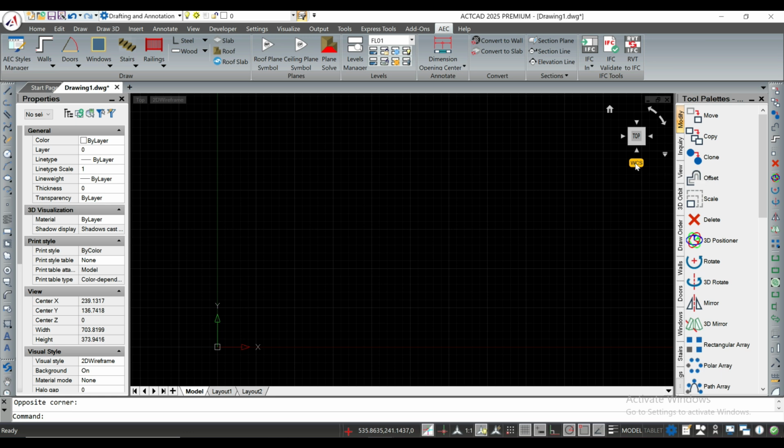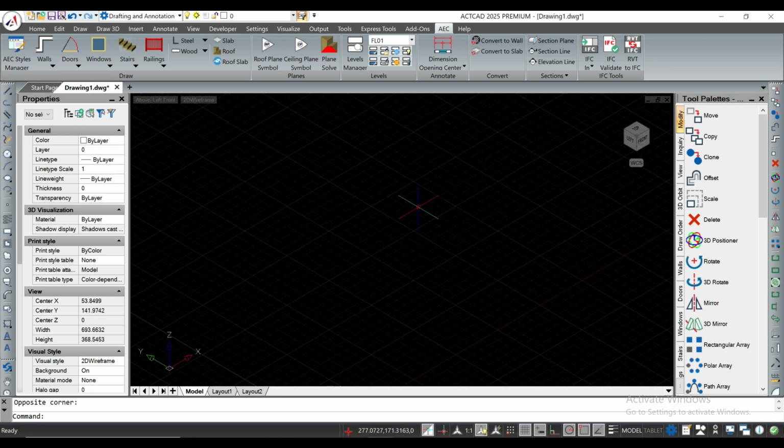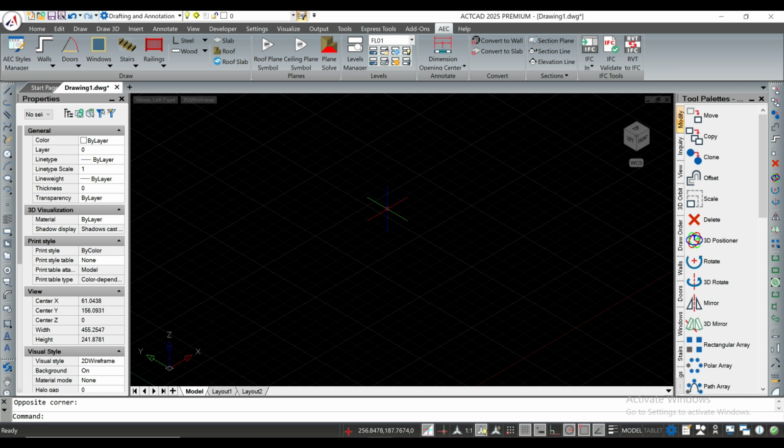The icon at the bottom that reads WCS allows quick access to any custom user coordinate systems you may have or the orthographic projections. As we saw in the viewport tools, the two curved arrows will rotate your view 90 degrees from the current Z-axis. And finally, in the middle, the cube has arrows around the edges, which provide quick access to the back, front, and sides. When you click on the main tile of each side, you'll go right to that view. Finally, each corner of the cube is a shortcut to view your model in the corresponding isometric projection. I'll click on the southwest isometric corner to duplicate what we saw using the viewport controls.